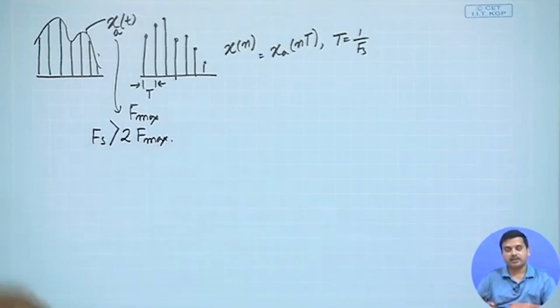So, this is the criteria that we had seen in the previous lecture. Going by what we have discussed, we can take a tiny example to see how you would choose the sampling frequency, because that is the important parameter which one should use when taking a particular analog input, so that you have an appropriate signal out of it.